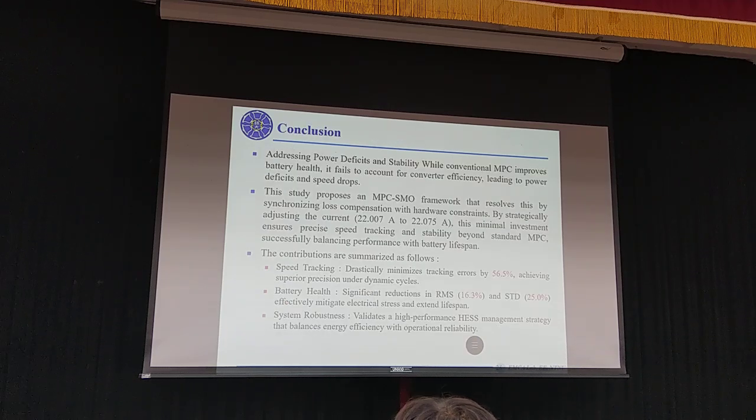Conclusion. We successfully addressed the power deficiency and speed drop caused by converter inefficiency by integrating loss computation with predictive control. Our MPC with SMO framework achieves superior precision beyond standard MPC.